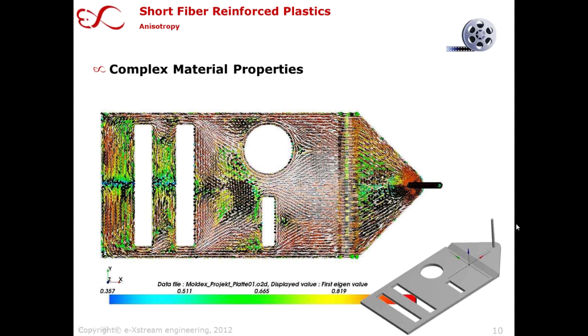So we can take a look at the fiber orientation as on this slide, and again we come in with a fully aligned flow. We hit the barriers. What it creates is flow lines, so you have a change of highly aligned fibers in this 2D example here. And then finally, when the flow hits in a static fashion, you have the typical weld lines in your part.